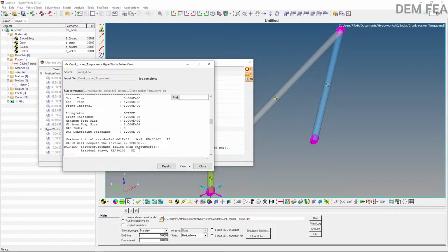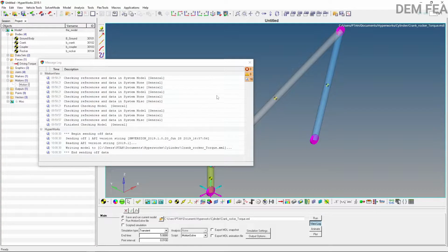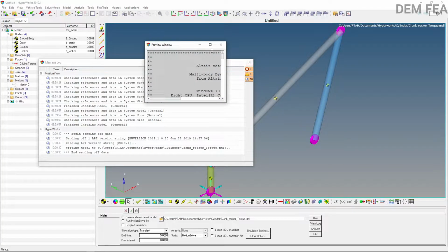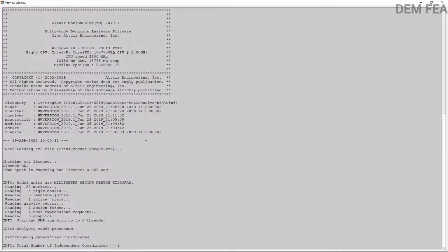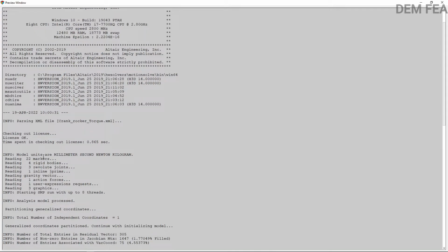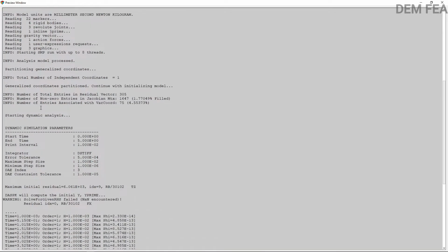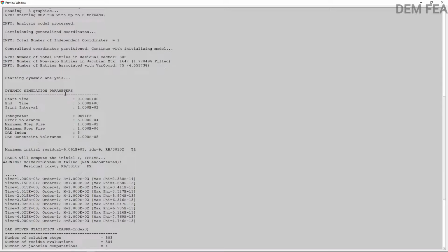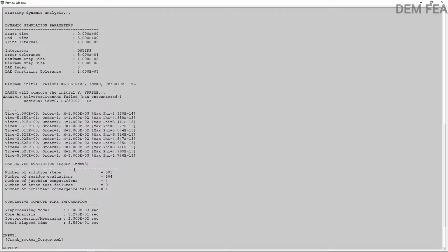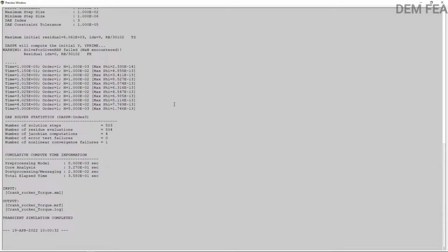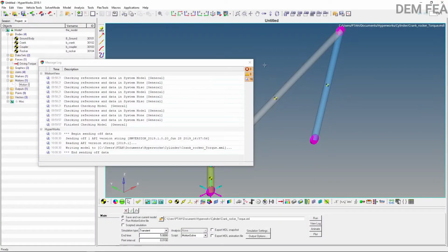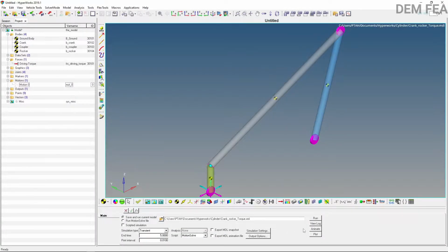Solver failed. As you can see, there is this warning here. So you can come here and view the log. We expand this and then we see what happens. We want to check the analysis if there is any error. It's a dynamic simulation because it's not fully constrained. Warning. So there are several warnings. That's because we have not put the mass properties. So let's come to the animation.